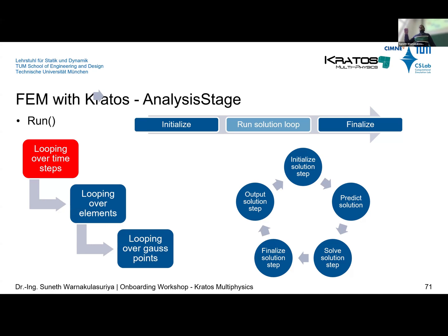As you know, if you are close enough to the solution, if you know almost exactly the solution, it's easy for any inverse or iterative methods to get the actual solution. So predict is supposed to do that, get closer to the solution, but it cannot get the exact solution, because then the solution is already there. Then you solve the solution step iteratively for nonlinear ones for each time step.